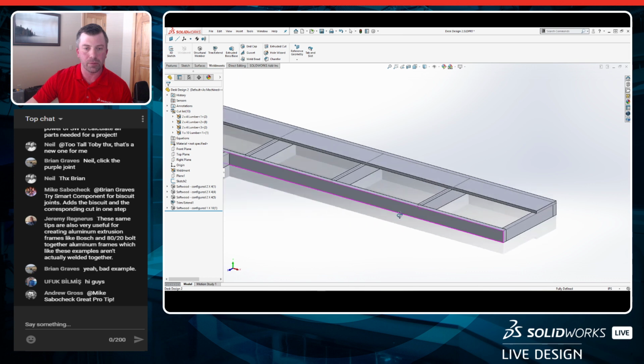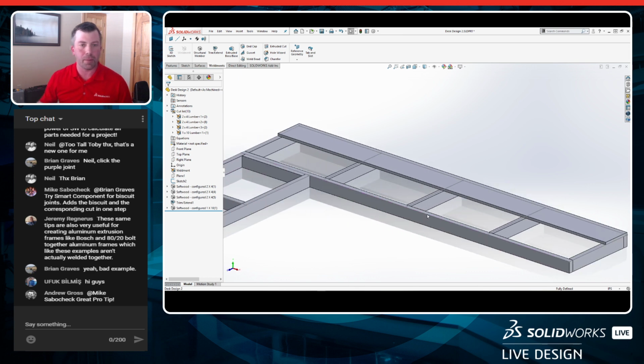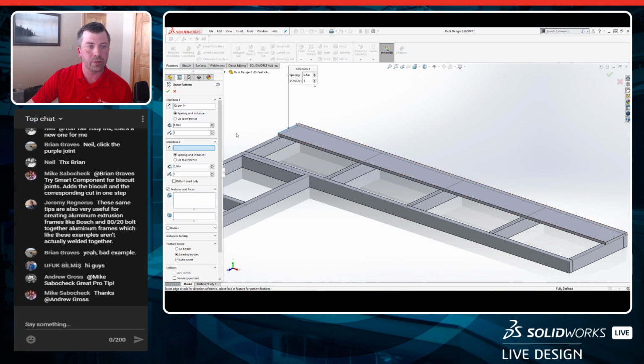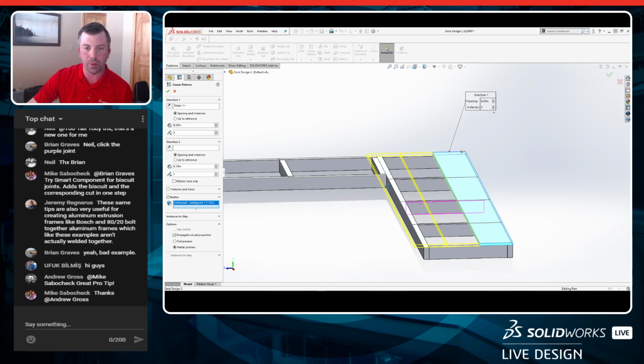So let's create a pattern first. Let's finish the top. I could create multiple sketches to do the same thing we've been doing, but all the standard features in SOLIDWORKS work great. So linear pattern. We'll give this a direction here. We're not going to use a feature. This is actually a body to pattern. And what is that? 9.25 inches is actually what a 1x10 is. So we'll do 9.25. We'll use the body option. This is key. Remember, we're working with bodies, not features. And we'll select that out and we'll do 3.